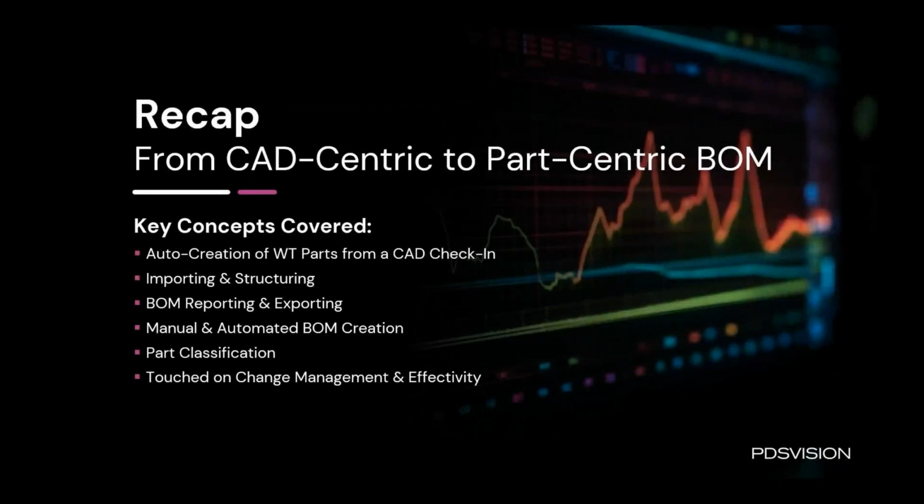So some of the key concepts that we covered then, we talked about the creation of these WT parts, okay, how we can derive those from the CAD data. We talked about how we can import information from Excel spreadsheets and define structures using those sort of third-party tools. Deepan also talked about reporting at a high level, of how we can extract information from our BOMs. A couple of different approaches, with manually creating part structures and the automated process of creating those structures as well, either from the CAD or again from importing Excel documents, that sort of stuff.